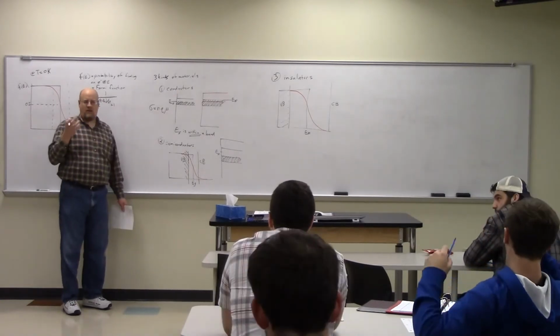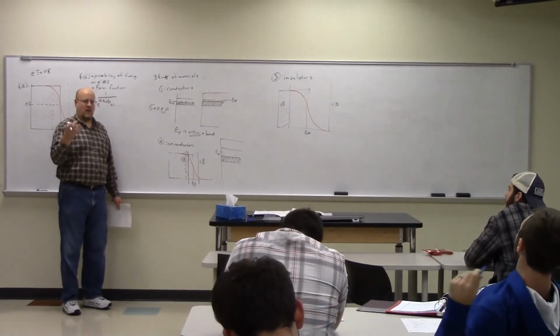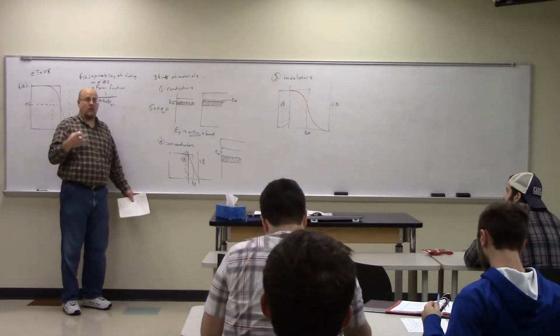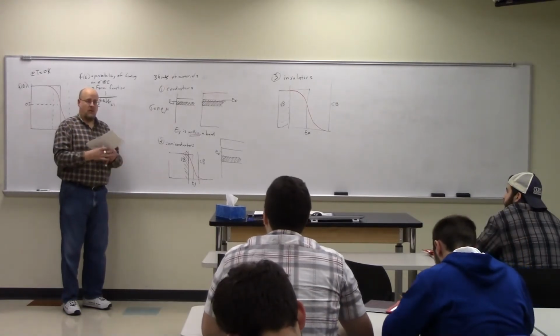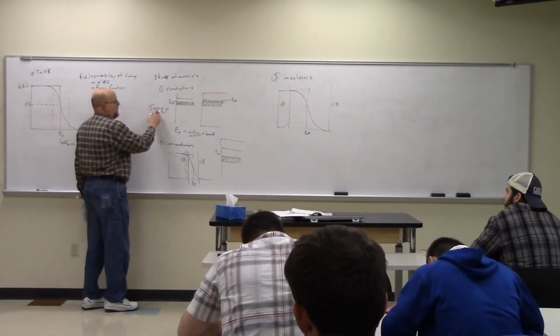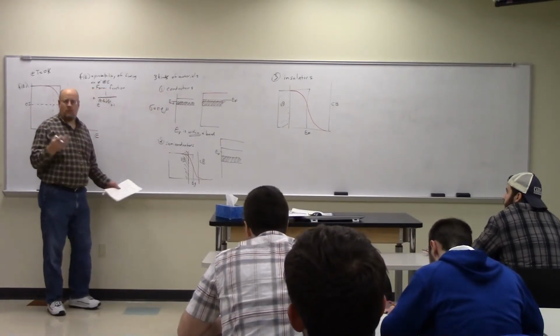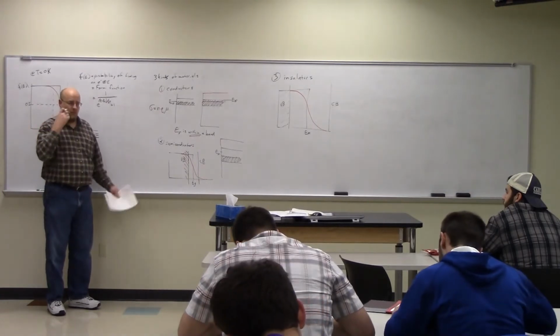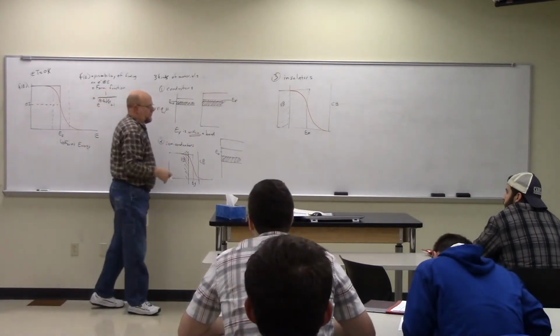Mu, on the other hand, is the thing that really affects conductivity that we can change. We can change the conductivity of materials by altering their properties, their characteristics. We can't change n because that's the band structure, the energy band structure we're given. And we can't change q because that's the charge.